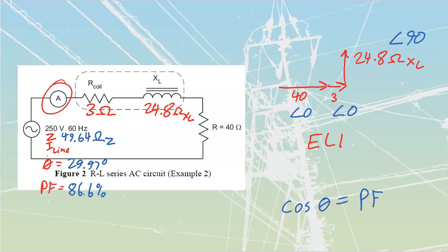Now, if you work along inside of your binder, you'll note that these values are a slight bit different from what's inside of the binders. By the time they get to this angular degree, they've gone through a number of other calculations, and so they've had a little bit of rounding error that starts to accumulate. Their degrees are going to be 30.6 degrees for the phase angle of the circuit. They're going to say that the power factor is a straight 86%. That's fine. They've used a different methodology to get there, and because they've gone through all those steps, we've just had propagation, or carrying over, of that error from step to step. We don't really want to see that, so we want to go as accurately as possible.